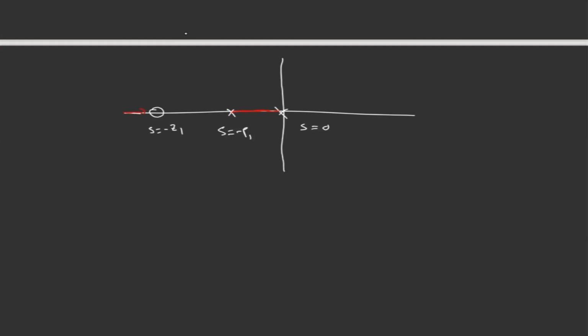This is quite sure. The root locus will break away somewhere in between, and it will go like this. So it means if we add a zero to the system, the system will be more stabilized. For any values of K, the locus is always on the left-hand side.